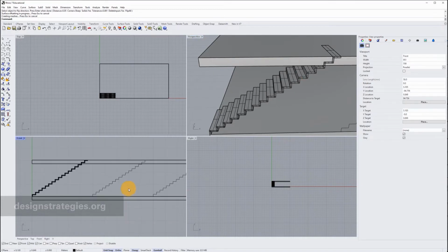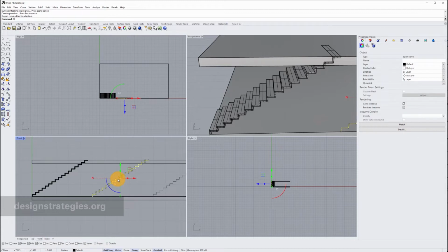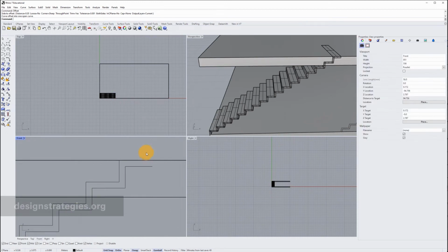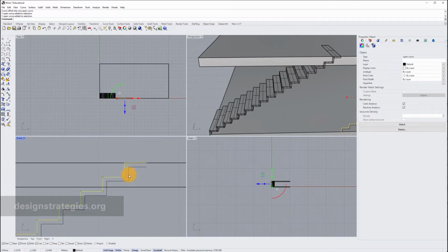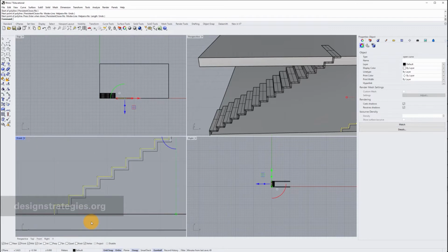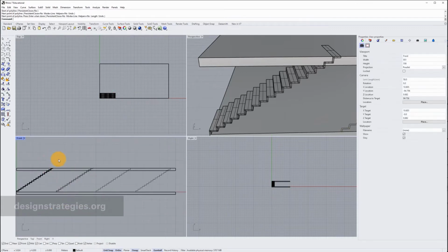You can obviously also offset just the line or the curve. Just go into offset and you choose the direction, and you say here also 0.15. But here you have to see that these are two open curves, and you probably have to connect them. And with this, you still have to draw one line here and the other one here. Select everything and then extrude this. It's obvious.